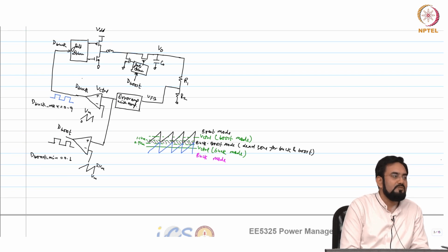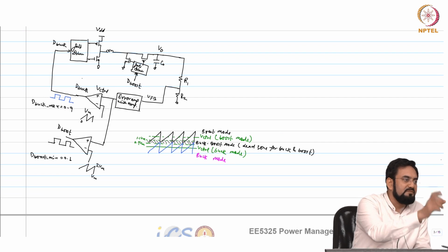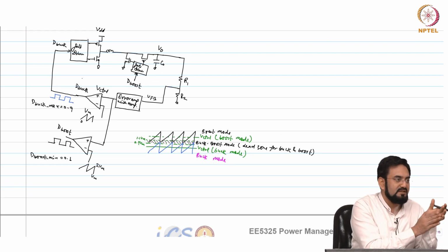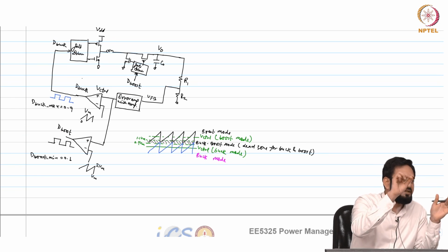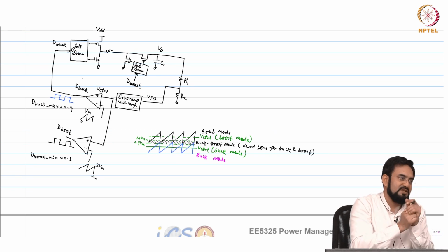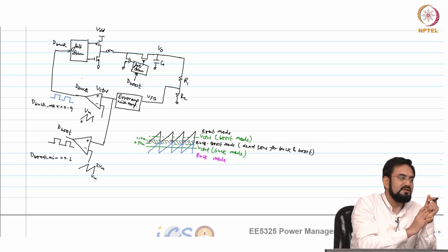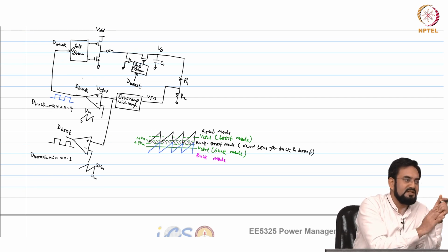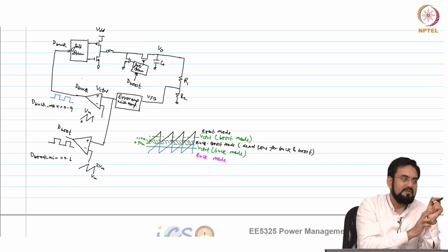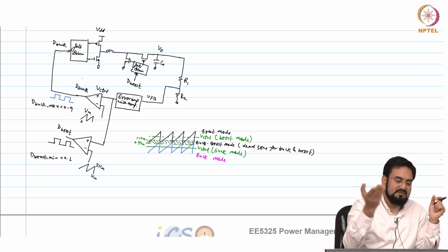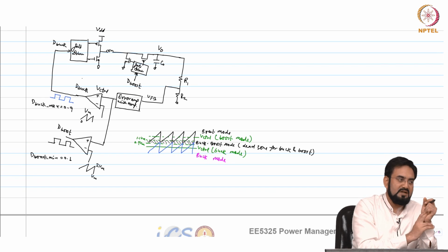No, it won't be open loop. In the closed loop, you have a subtractor. So, this 100 millivolt you have fed, when you transition, before that the 100 millivolt is actually 0. The moment you transition, you make that voltage 100 millivolt, so the duty cycle will immediately change, and from there it will take on.